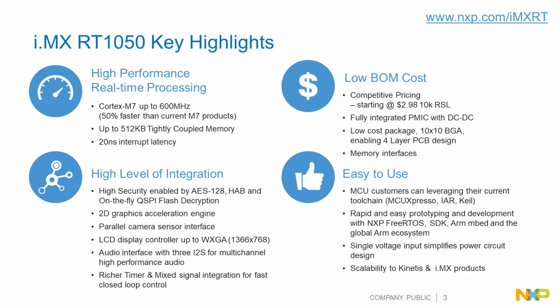In terms of high level of integration on the bottom left, we've brought over a lot of the characteristics that you're used to in our i.MX 6 product line. So we brought in encryption engines, high assurance boot, and on-the-fly decryption on the quad SPI, so when you're interfacing with external memories. We have a 2D graphics acceleration engine as well, and a parallel LCD interface.